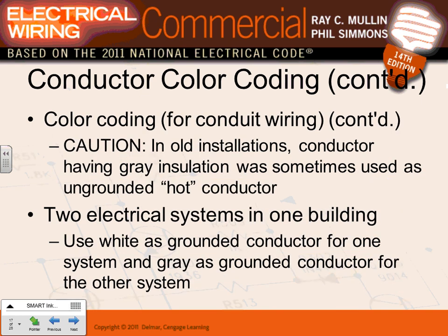So that's basically what this is. This is color coding. You guys know, not electricians, but gray in the past has been used as a hot, as an ungrounded conductor. We actually have in one of our buildings, the gray is used as an ungrounded conductor.